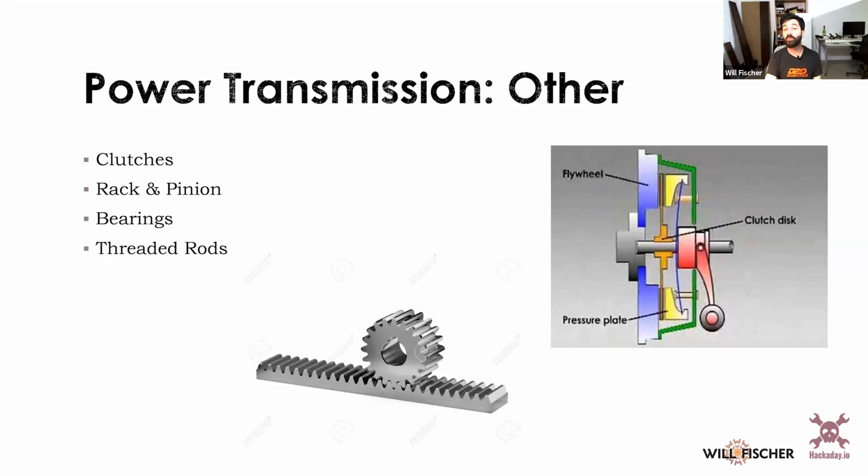Okay, there are some other ways you can transmit power. Right here, I've got a rack and pinion. That allows me to take rotational energy and convert it into linear energy. It's a very efficient way to do it, but I have a limited range.